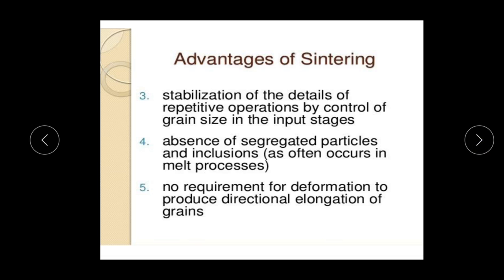Let us discuss some advantages of the sintering process. The stabilization of the details of repetitive operations by control of grain size in the input stages. The absence of segregated particles and inclusions, as often occurs in melt processes. No requirement for deformation to produce directional elongation of the grains.